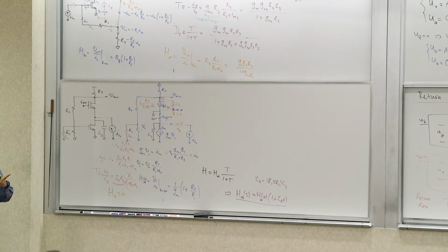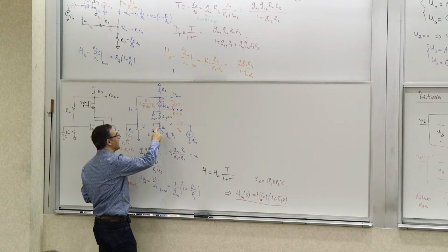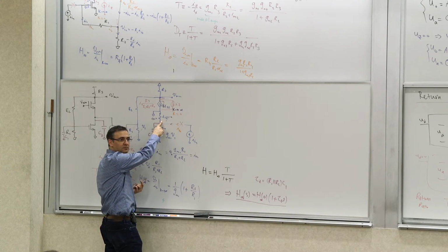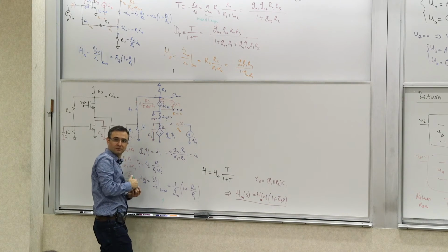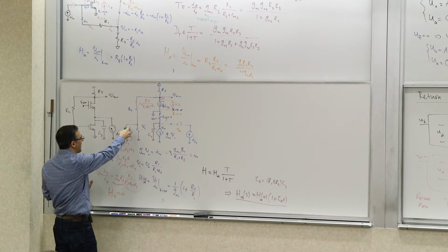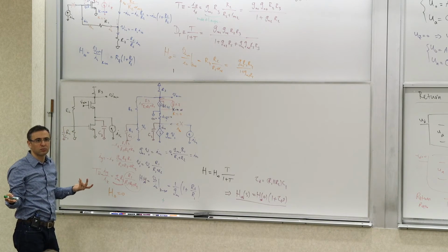So there are 3 calculations really, with the k0, k1, and k infinity. So k is 1, and you have an Ix and an Iy. How many zeros and how many poles? How many degrees of freedom do we have? We have 2 capacitors, right? And we are not going to k infinity, so this voltage is not necessarily 0. So this capacitor is there, and this capacitor is there, so these two are not forming a capacitive loop. So you have 2 poles, exactly.